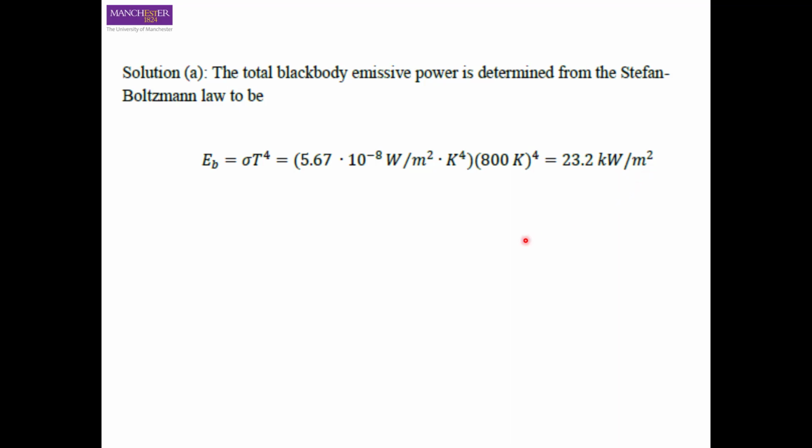Okay, and now if we look at part 2, we are asked to calculate the amount of energy that is radiated from this ball in 5 minutes. We know from our basic understanding of thermal radiation that Q radiation, the flux of radiation emitted from a ball, is equal to sigma T to the power 4, as we saw in the previous slide.